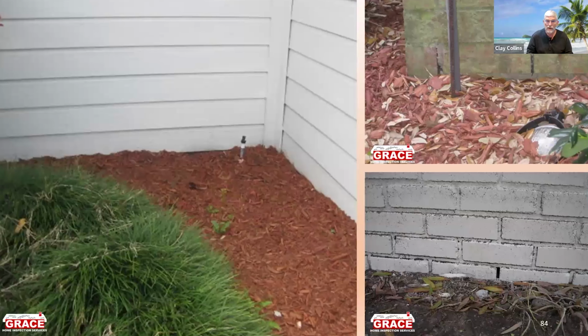Poor drainage and high soil. That's flat as can be. It's in the re-entrant corner of a house. I don't have any information from the photograph on whether there were downspouts or gutters or not, but that's not going to do anything but hold that. Same thing with the upper right. That is an irrigation line, and at the bottom, you see that there's some flat work. So you have this area between the brick and the flat work, like a sidewalk or a walkway. And they've created a dam, and they filled the dam with mulch, and it's over the weep holes.